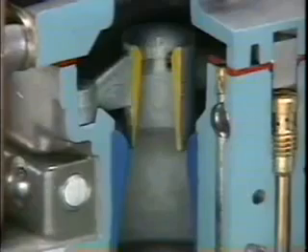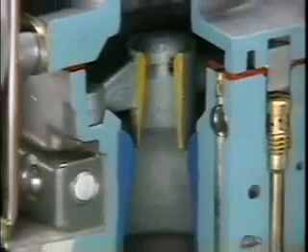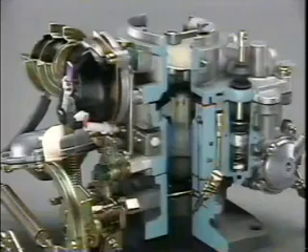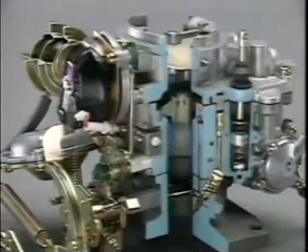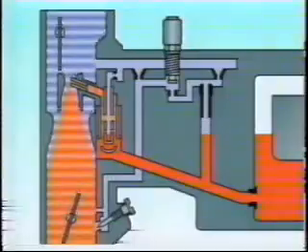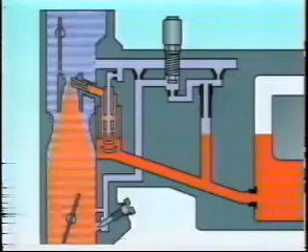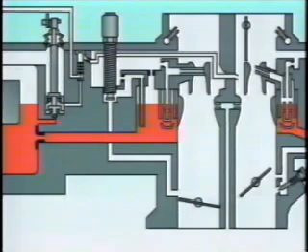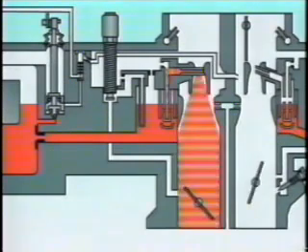This is how the air-fuel mixture is regulated during idling and at low and medium speeds. However, this alone will not produce the power needed during high-speed operation. This is why the double-barrel carburetor has a secondary barrel. The construction of the secondary barrel is the same as that of the primary barrel. It has a high-speed circuit, which is its main circuit, and a low-speed circuit which prevents the mixture from becoming too lean when the throttle valve opening on the secondary side is small.